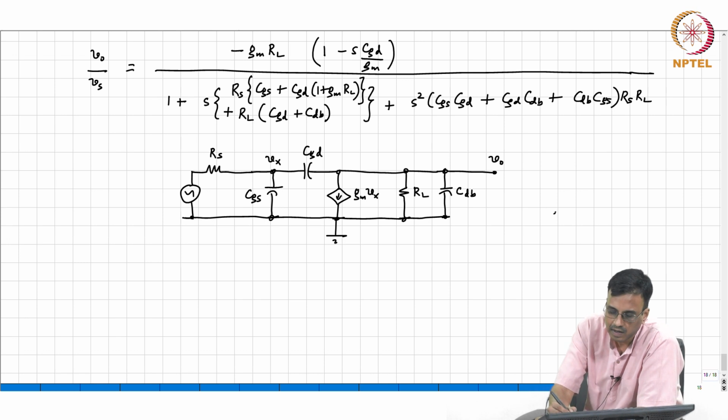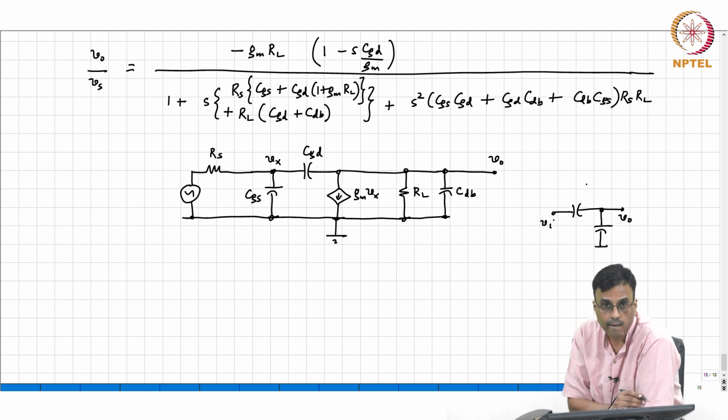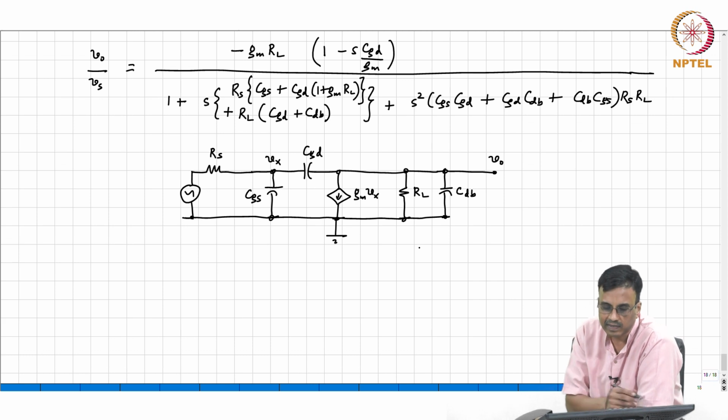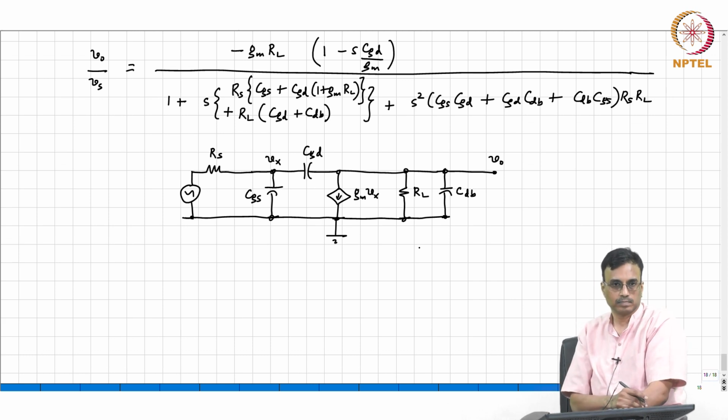And in fact, how many energy storage elements are there here? 2. What is the transfer function from input to output? It is a constant. So, you can see that the number of energy storage elements is not necessarily equal to the order. Okay. So, with that in mind, because there is one capacitor loop, it makes sense that the denominator is second order.